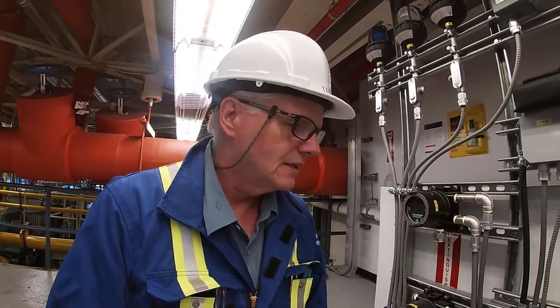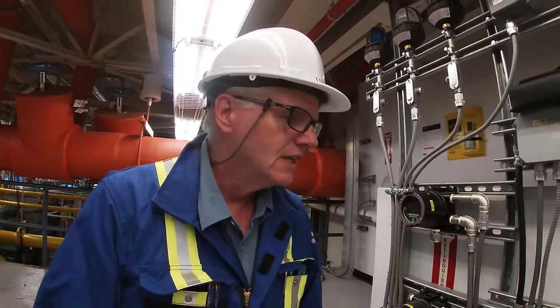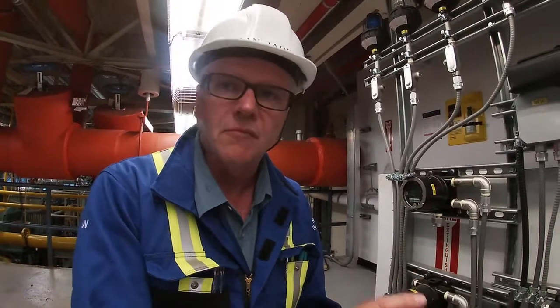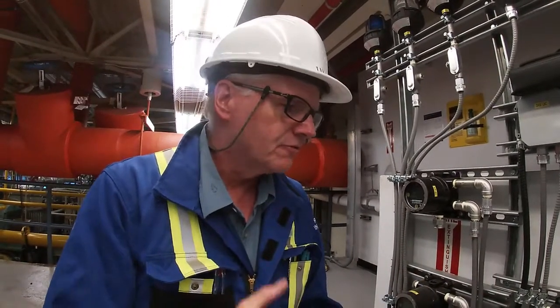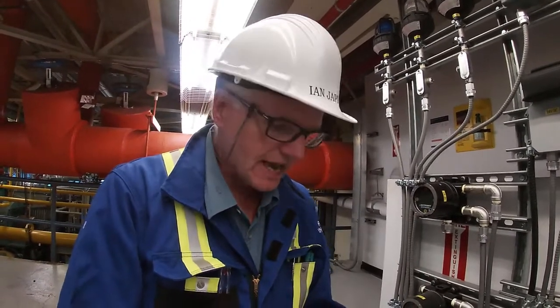two workers ended up being asphyxiated by ammonia gas from the chillers. They knew that there was a leak in there, and they went back in and worked. Pretty sad, they lost their lives. So there's a big push to understand ammonia detection as well. The operators asked us to add this in, and I was more than happy to put it in for them. So we've got three different gas heads.